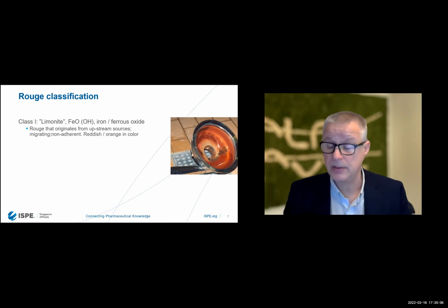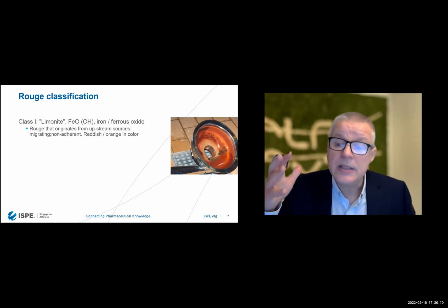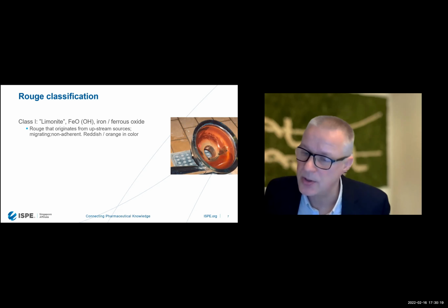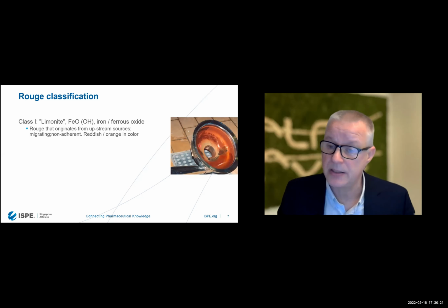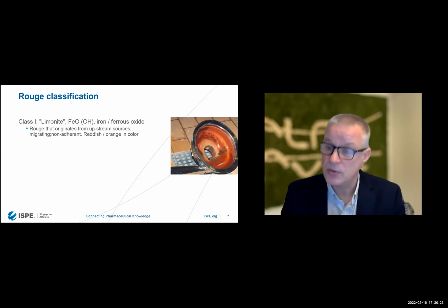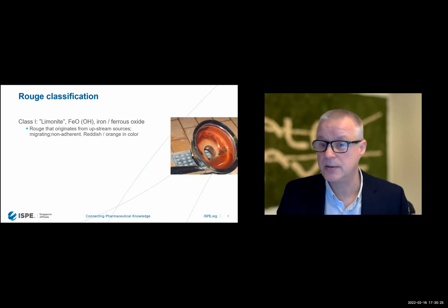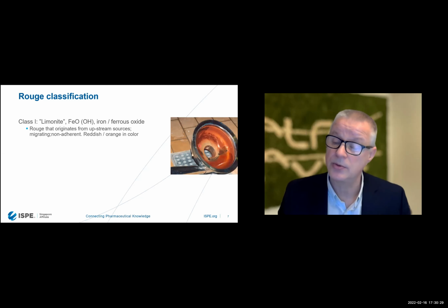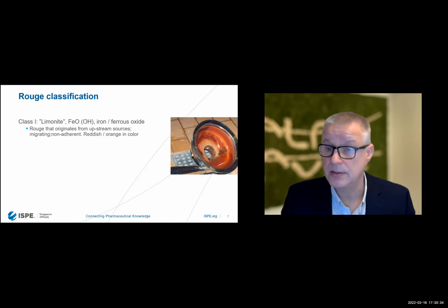You don't need, as I mentioned in all the other questions, to have a special check or control of rouge in the system, visual and invasive control. You only do it when you do service and maintenance. And then you must separate the pump or disassemble the pump to check for the rouging and also replace the shaft seal. So do that at the same time. That's what I would recommend.